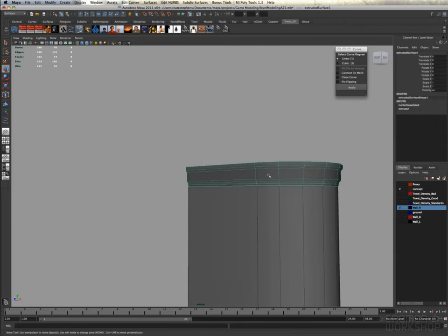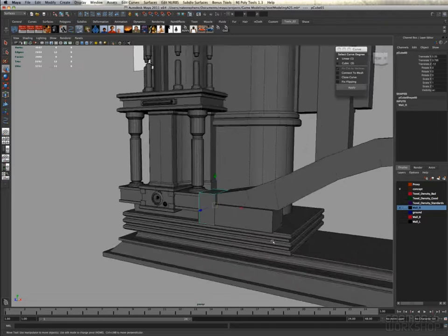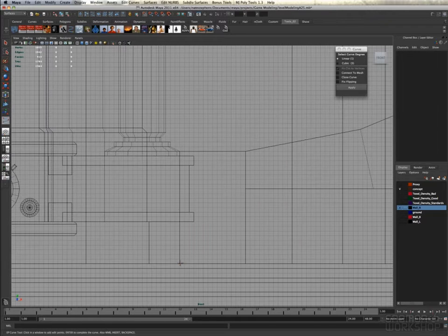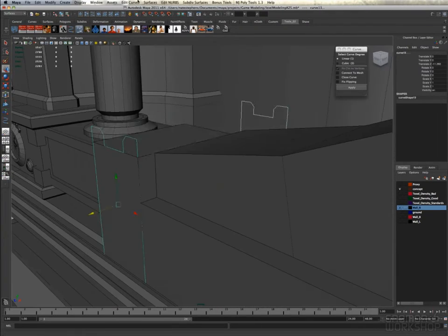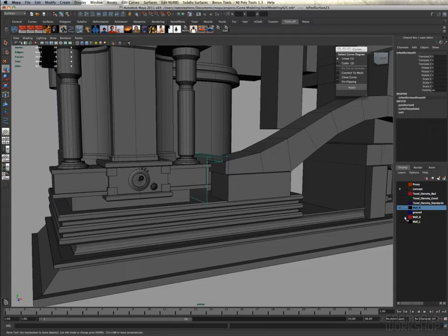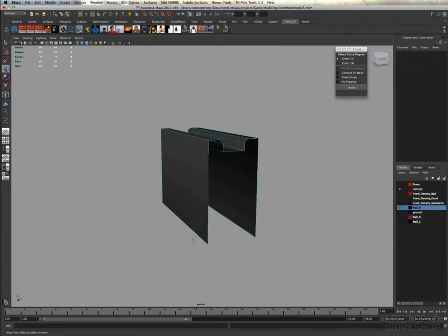What I've done is I've created a hotkey for toggling back face, and hitting that will show me if something that I recently lofted or revolved needs to be reversed. But it's definitely something to keep your eye out for if you model with curves, is making sure that the face orientation is correct.